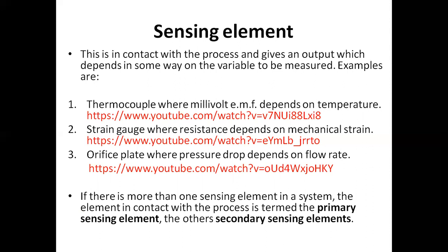A thermocouple takes thermodynamic temperature or heat and gives us as its output an electrical signal in form of a millivoltage signal that is somehow dependent on the temperature being probed.